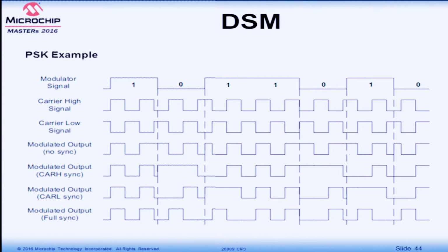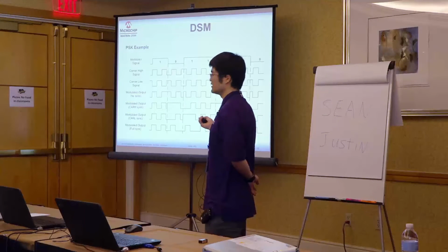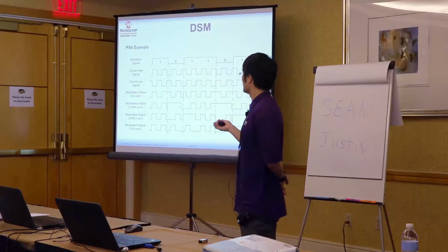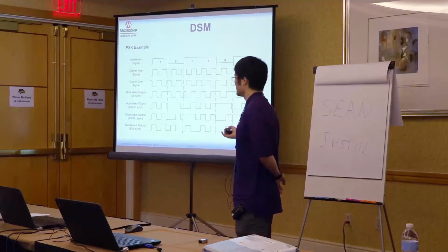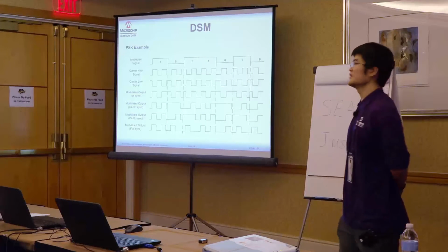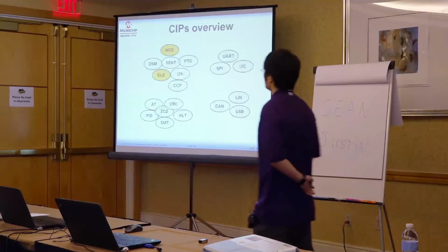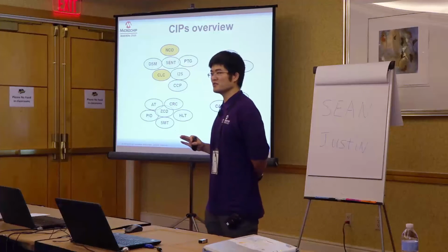If I do PSK, I apply high and low with a phase shift. I can apply no synchronization, high side, low side, and both sides. What you will see is the waveform gets a little bit distorted depending on what synchronization you choose, for better or for worse. So that's the DSM. Any questions on this module?